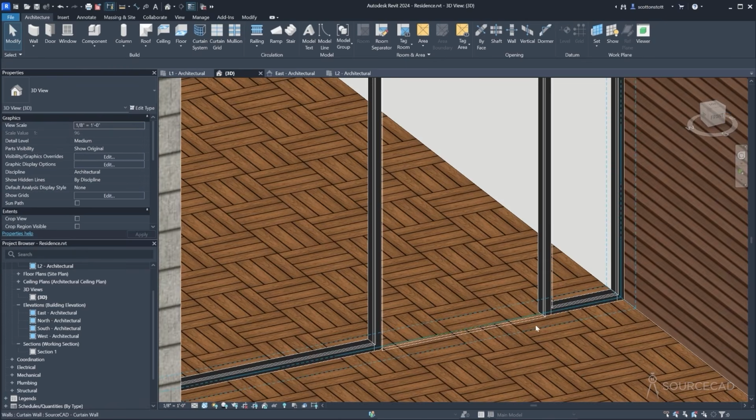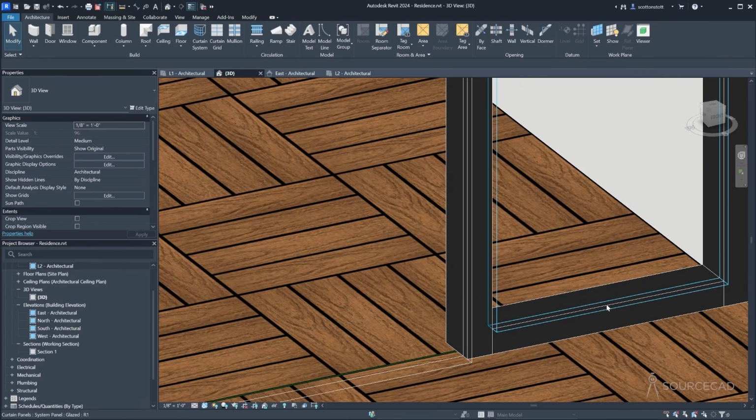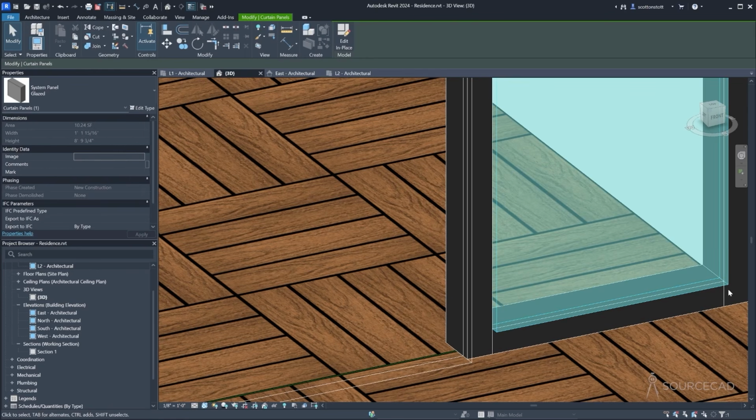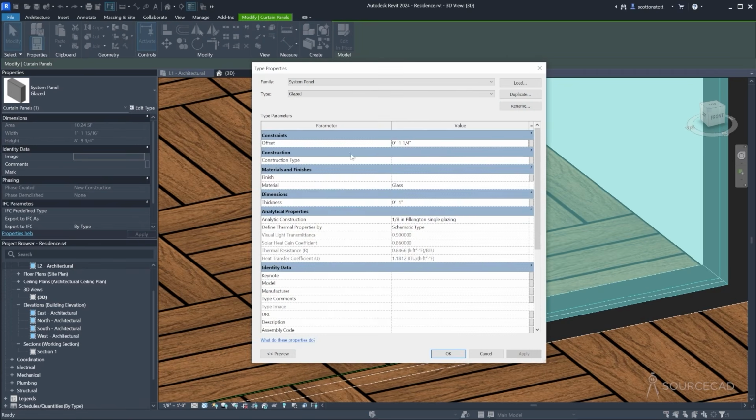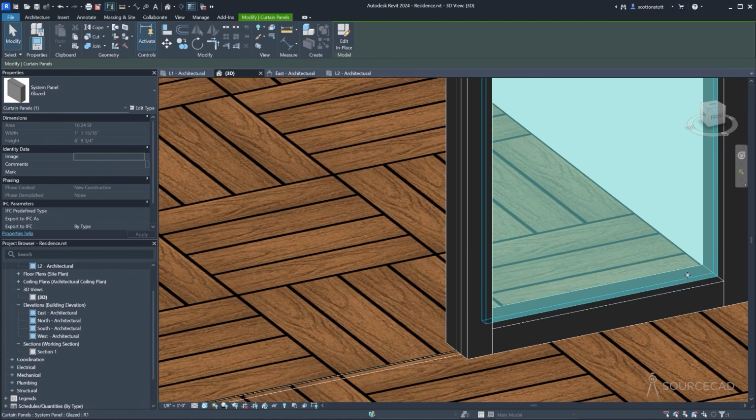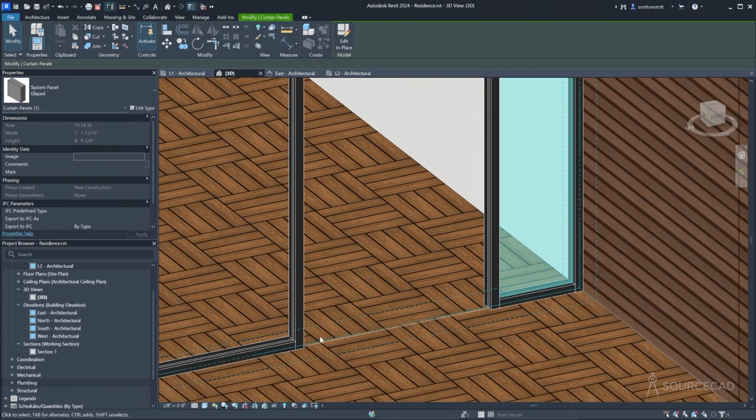Now down here we want to have a door, not a piece of glass. And in fact, all of these pieces of glass, if you select this panel, you'll see that it's right on the front of the extreme edge of the panel. Maybe it's even sticking over. So if I edit the glazed panel, I can change the offset value here, and the thickness of the glazing is going to be less. And by doing that, the panels recess a bit into the framing and so on. And that happens everywhere because I changed that type. And all of those panels, all of those glazing panels use that same type. Now for this panel here, this is also a glazing panel.